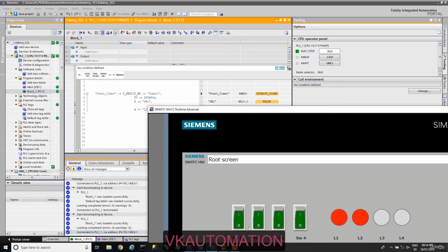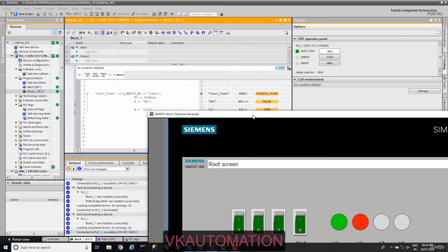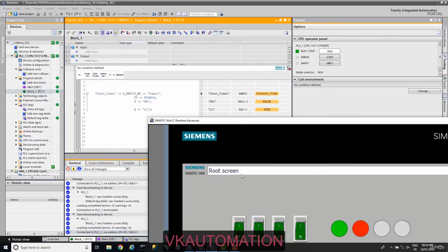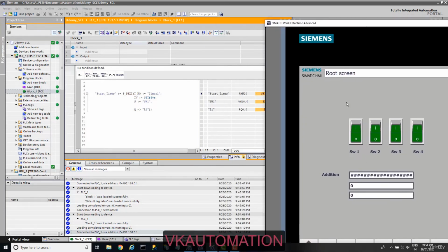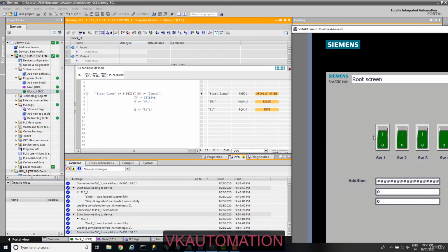This 40 per second is the old timer setting. So here you can see I have turned on the switch, and again turned off the switch, meaning I have given only one pulse. I only give one pulse and it extends that pulse to stop the timer after a predefined time. So the pulse timer needs this switch 1 continuously on, but this pulse extended timer doesn't need continuous input. It can run for only one pulse. You can see here.